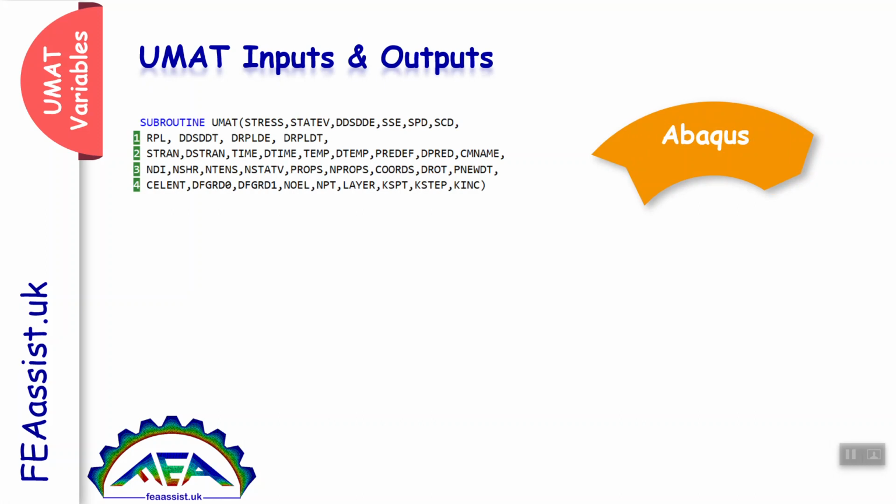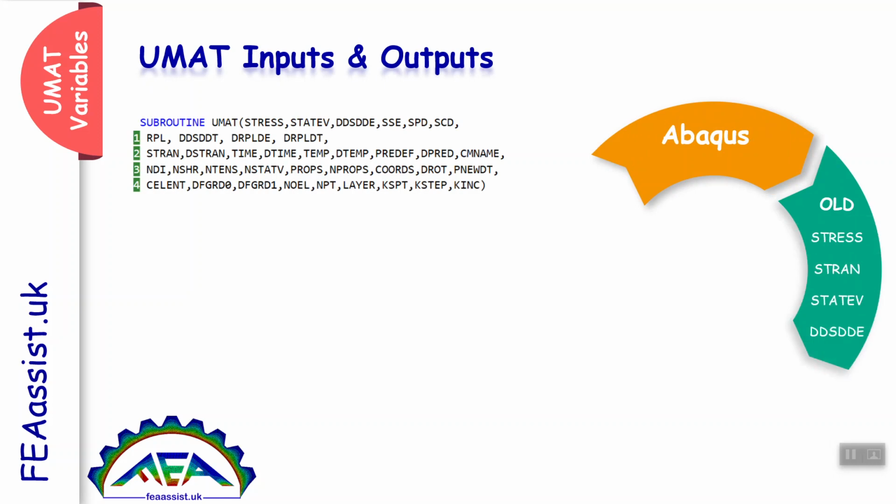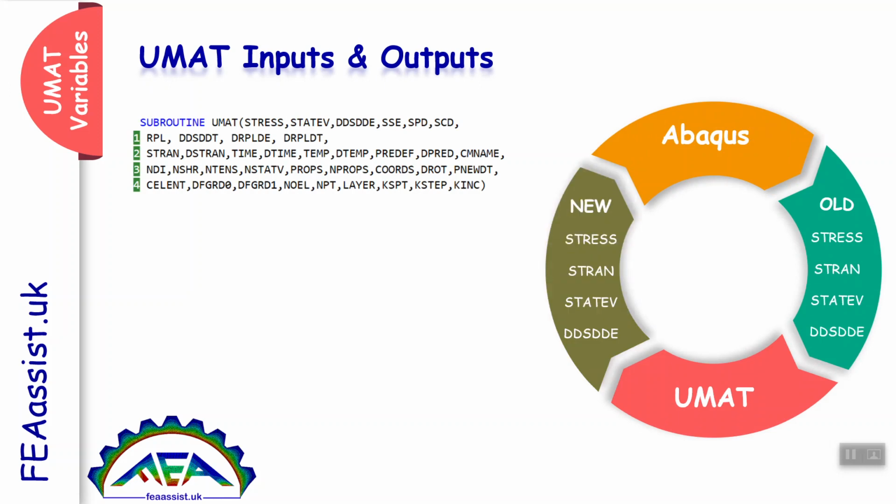Actually, all these variables are computed in Abaqus and transferred to the VUMAT. In the VUMAT, we need to write some equations based on our constitutive behavior to recompute all these variables, and return them back to Abaqus. This is how Abaqus and VUMAT interact with each other, which is necessary to write a well-working VUMAT.